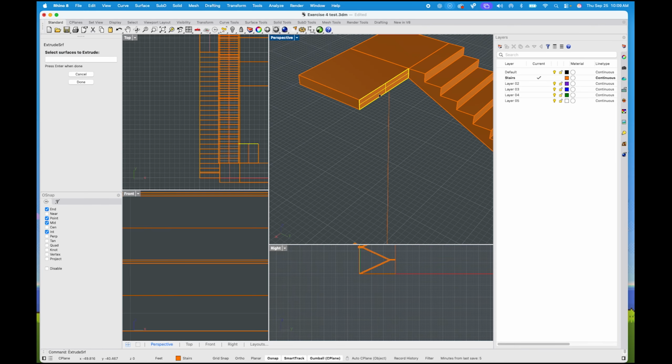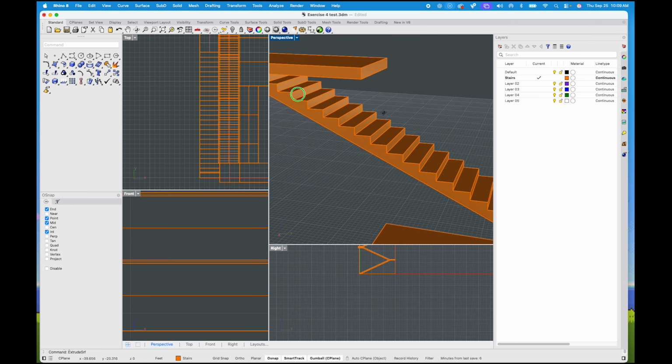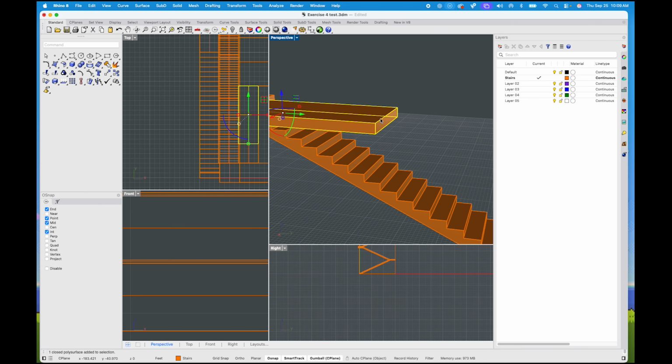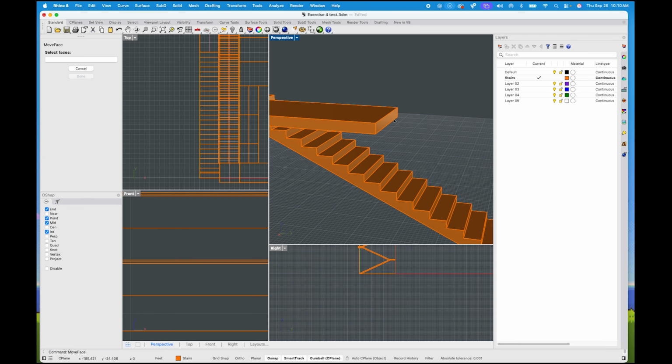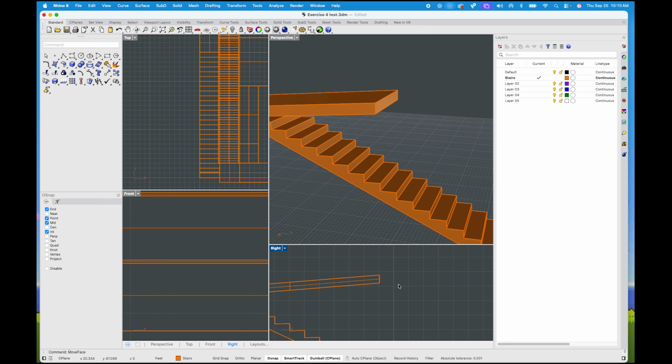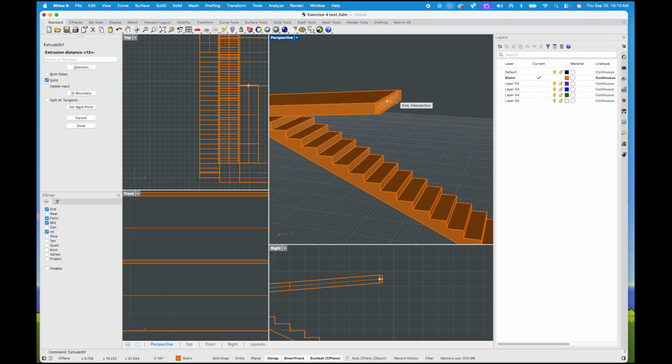I'm going to add another ramp because I don't know, I feel like it. So I'm going to go out 12 feet again just to make it easier on the math. And again, so we can see that process of moving this face again. So move face. Now that's something push and pull can't do, right? Can't just move the face. Are you kidding me? 12 inches. And enter. Again, extrude. To be fair, I'm kind of going fast so I can actually get to the rail portion.